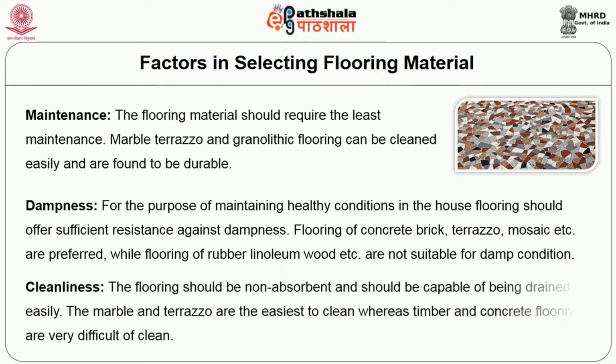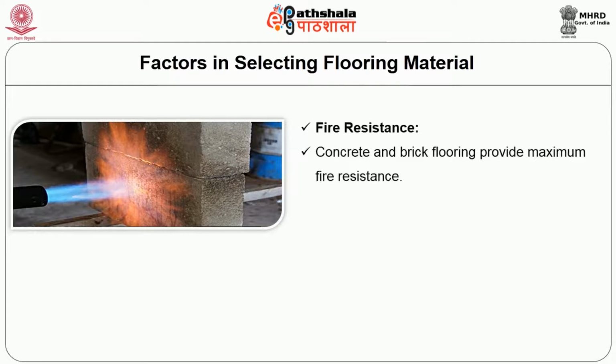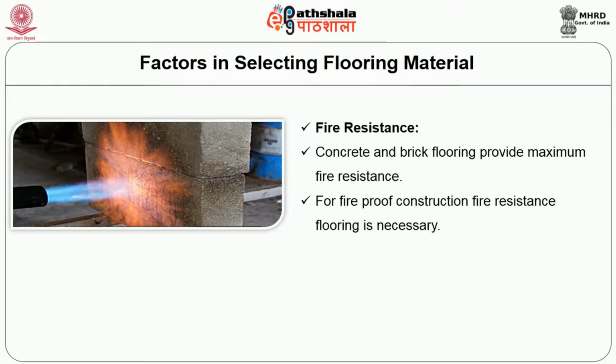The next one is cleanliness. The flooring should be non-absorbent and should be capable of being drained easily. Marble and terrazzo are the easiest to clean, whereas timber and concrete flooring are very difficult to clean. The next one is fire resistance. Concrete and brick flooring provide maximum fire resistance. For fireproof construction, fire resistant flooring is absolutely necessary.